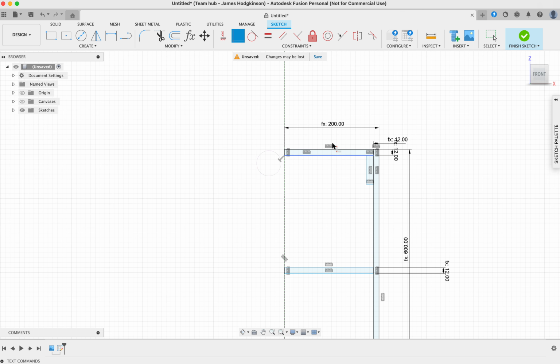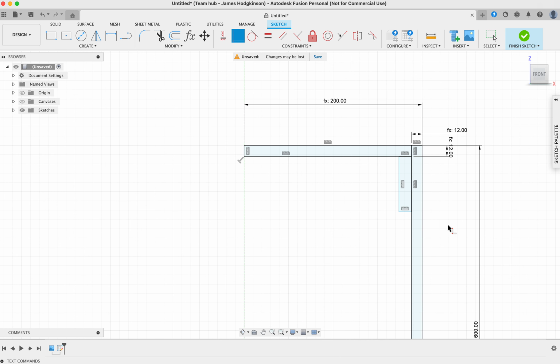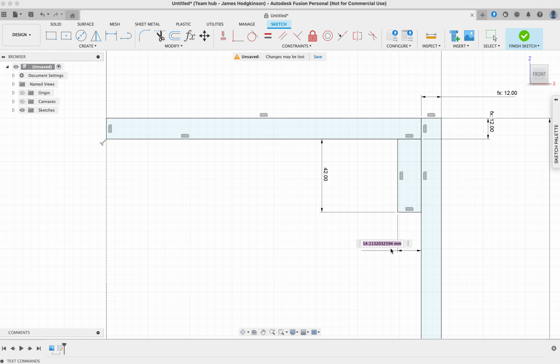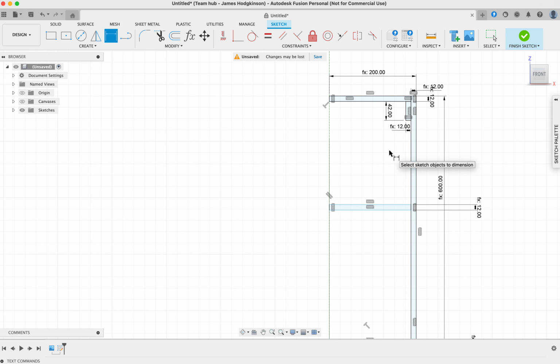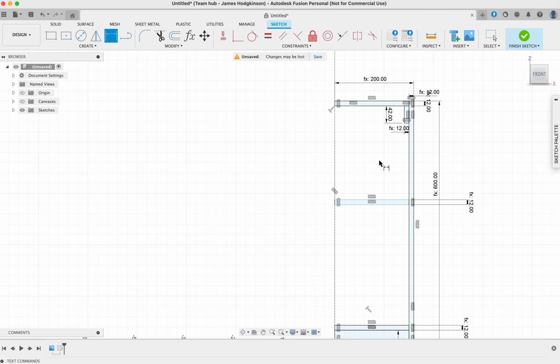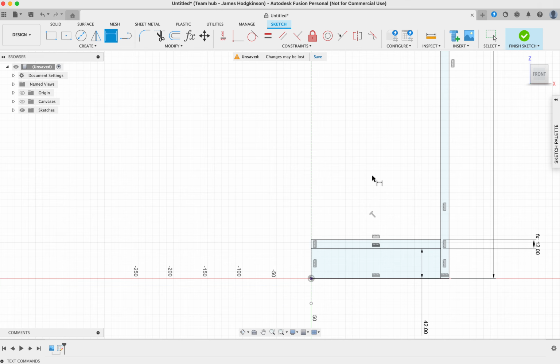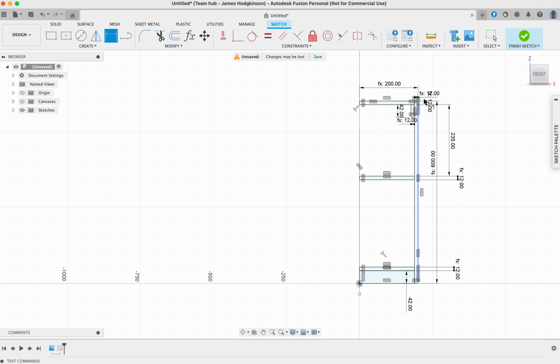Now, because we have a height and a width, these are defined. Because we haven't given this anything that's not defined yet, I'll give that a dimension of 42 because we're working with random arbitrary things, and we know its thickness, so now it's defined as well. We haven't said where the shelf is, so it's now 235 mil from the top. So now it's defined. Everything else is defined, so we have black lines everywhere.